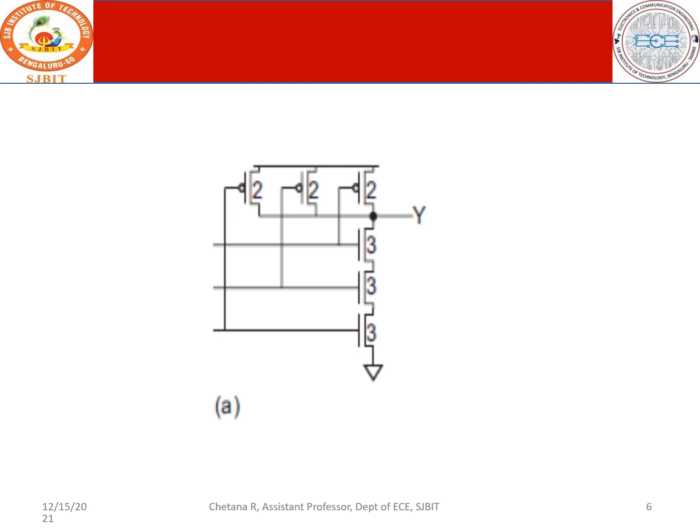1, 2, 3, 3 inputs, and the inputs are shorted with respect to the NMOS and PMOS, and the ratios are given here. In this example, the width for PMOS is given as 2, 2, 2, whereas for NMOS it is 3, 3, 3. As a result, what should happen to the respective capacitances and resistances? Resistances are divided by the width factor given across the device, and the capacitances are multiplied.